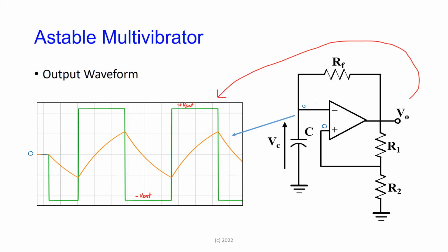Remember, here is at 0. So the voltage on the capacitor changes, and the little leakage current starts to increase this a little bit. The capacitor starts to try to charge. The instant that charges, this point here, you remember what the op-amp is, this is the inverting terminal.